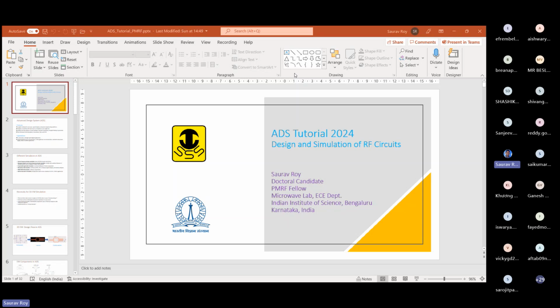So I saw a couple of submissions already. One person, I forgot the name, but somebody submitted only the schematic. But I must tell you the schematic is actually nothing. You have to do the layout and microstrip circuit, not just add schematic components from ANSYS or ADS or AWR or whatever and show the schematic simulation. Because that obviously will not work in the final layout. You must do the layout circuit, which can actually be printed or fabricated.